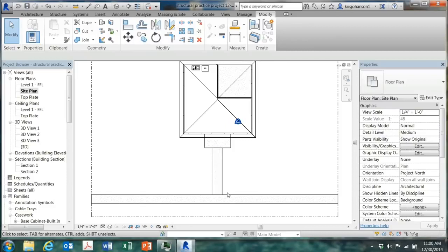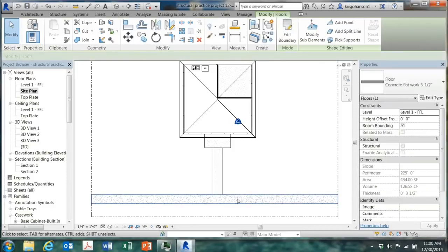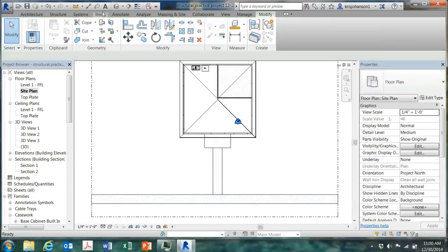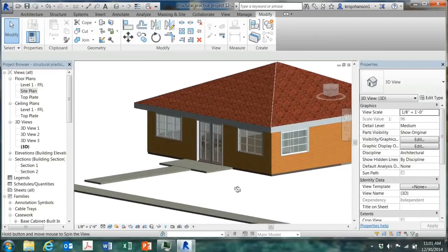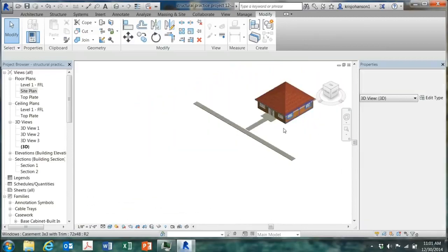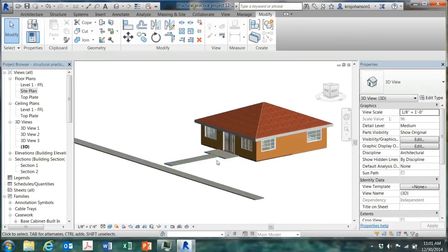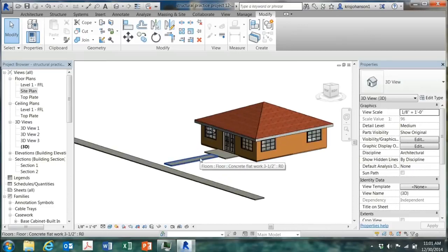Click on Modify, and that portion of sidewalk is at 0 feet again. I'm going to make that lower than the rest. Assume the front yard slopes down. So I'm going to make that -1 foot and apply that. I'll click on Modify. Let's go to the 3D view now and see what that looks like. So we have 3 sections. So our next challenge is to put a slope on this section so it joins up with the other two.